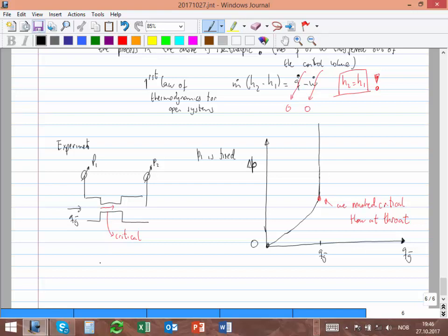And that basically is, for example, if we have a piece of metal, and that's supposed to be a hand, and that's metal, and you bang it, the sound or the vibration propagates almost instantaneously through that metal. So you have a velocity that transmits the change in the pressure fluctuations in that material. That's for a solid. But when you have a liquid, you have exactly the same. You have a velocity at which the pressure change travels, and that velocity is called the velocity of sound.